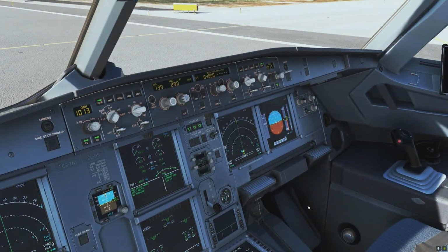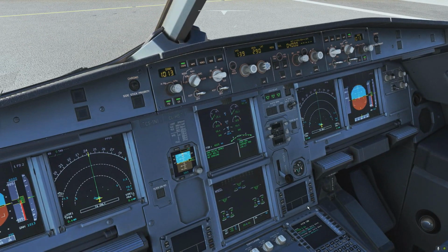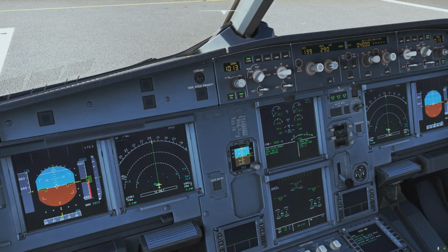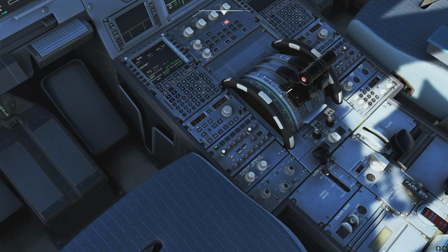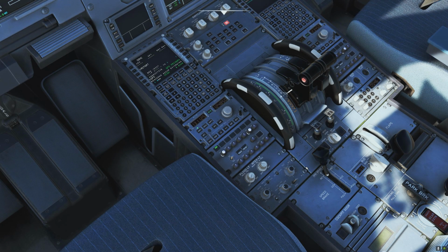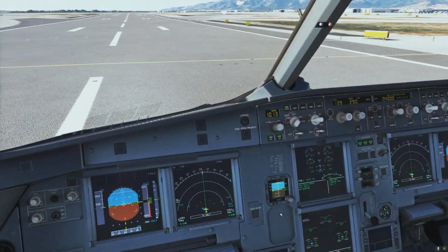It takes a bit of practice, it takes a bit of getting used to. I have to admit, at the beginning when I started flying the bus, it was a bit tricky for me, but by now I think I've developed a good feel for what I can expect, where I want to be, and usually it works out really nice. And like I said, if you really mess it up, open descent, put the speed up if you can, and then there's always the speed brakes. Some people are very reluctant to use them, but this is exactly what they're here for, so make use of them.